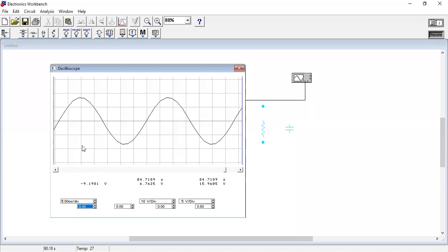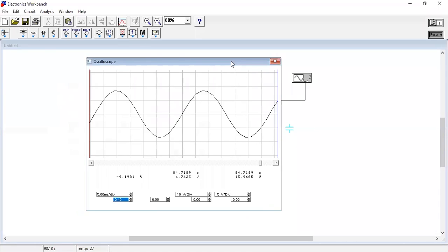Okay, so in your procedure guide, the theoretical ripple factor equation, gamma, is equal to 1 upon root 3 into (2 f r c minus 1). So in this equation you can put the f value, that frequency value. Okay, and in this practical we need to find the output voltage with changes of capacitor values.